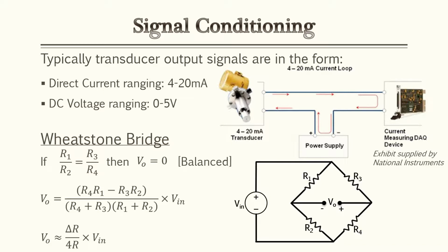Now, National Instruments provided a nice illustration there, where it actually has a 4 to 20 milliamp transducer with a power supply in line with it, and it's outputting to a DAQ unit. And that's actually very common out in the field.